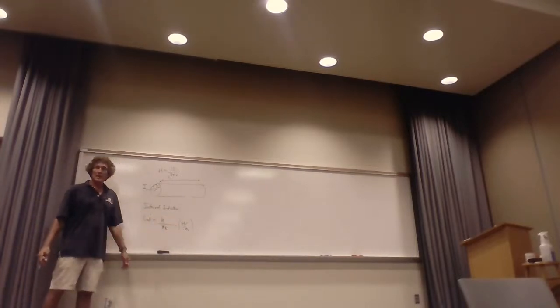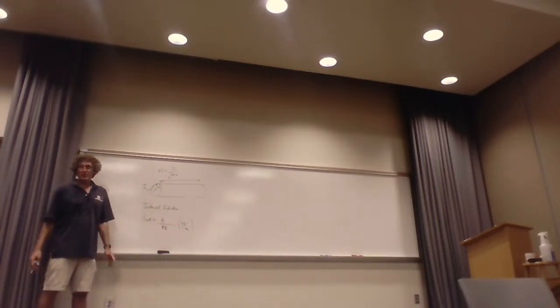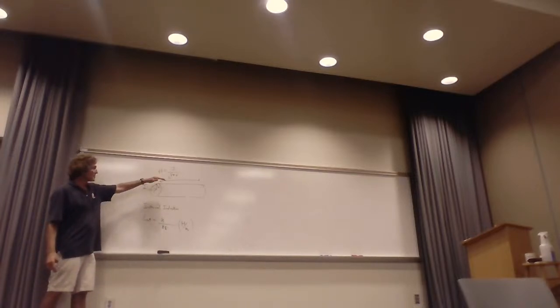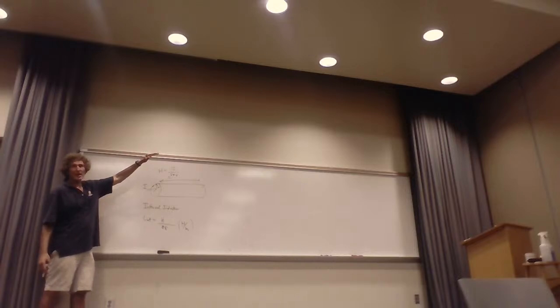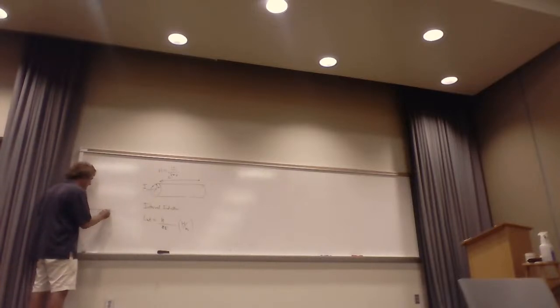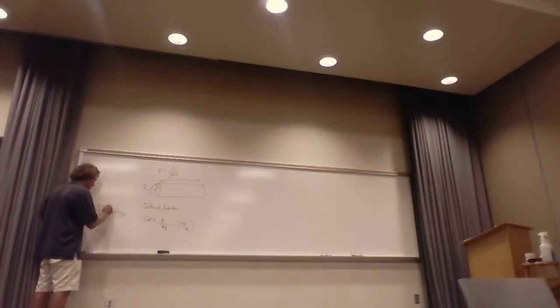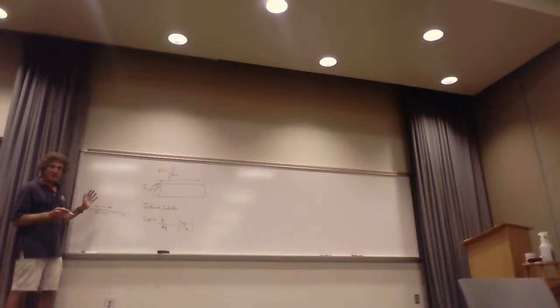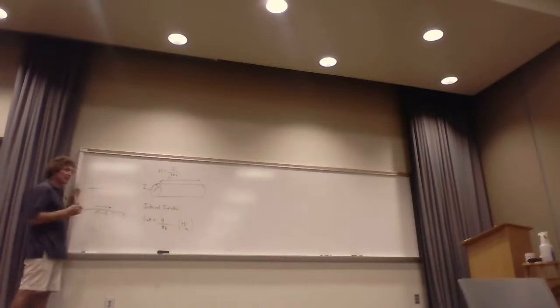All right. And here's the deal with this. We're going to get into this. There's this thing called partial inductance. When you talk about the magnetic field outside the wire in the external inductance, it depends on the return path. For instance, if you have a ground plane and you put a wire over it, you image a wire opposite, and the total magnetic energy out of that wire around it is much, much less than if you just have a wire hanging in free space.